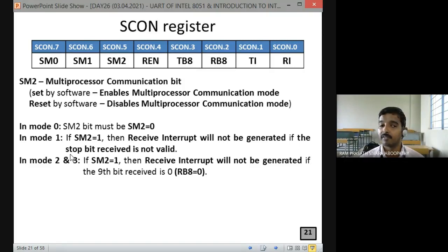அப்படின்னா மீனிங் என்ன? எல்லா மைக்ரோ கண்ட்ரோலருக்கும் நம்ம டிரான்ஸ்மிட் பண்ணக்கூடிய 8 bit டேட்டா போகும் with 9th bit as 1. 9th bit 1ஆ இருந்தா கண்டிப்பா என்ன ஆகும்னு சொல்லியிருக்கோம், interrupt generate ஆகும். That means whenever you send an address, all the microcontroller will get interrupt. Is it clear or not? கொஞ்சம் கேர்ஃபுல்லா கவனிங்க. இது கேர்ஃபுல்லா கவனிச்சா மட்டும்தான் புரியும்.